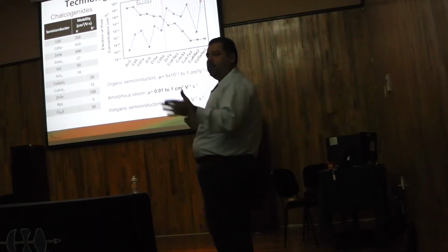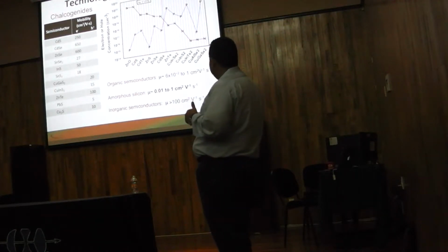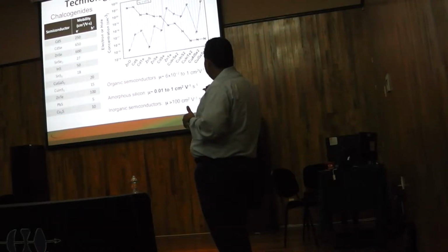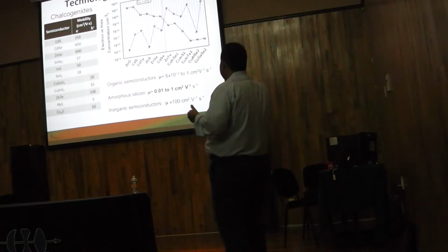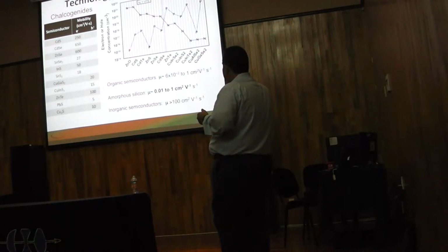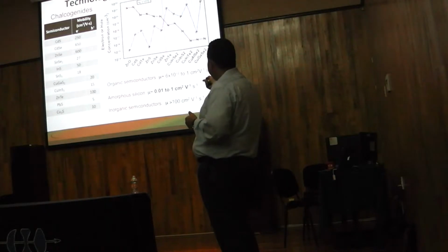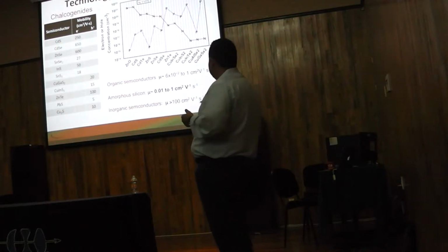That's just half of the equation here. The other thing is the electron or carrier concentration. So if we plot the electron or carrier concentration for a number of materials, obviously if it has more electrons than holes, it's going to be N-type. If it has more holes than electrons, it's P-type. What is interesting here is that zinc oxide is very difficult to make P-type, and the reason is that the N-type or electron concentration is pretty high. We need to reduce the N concentration about 6 orders of magnitude, which is very difficult.